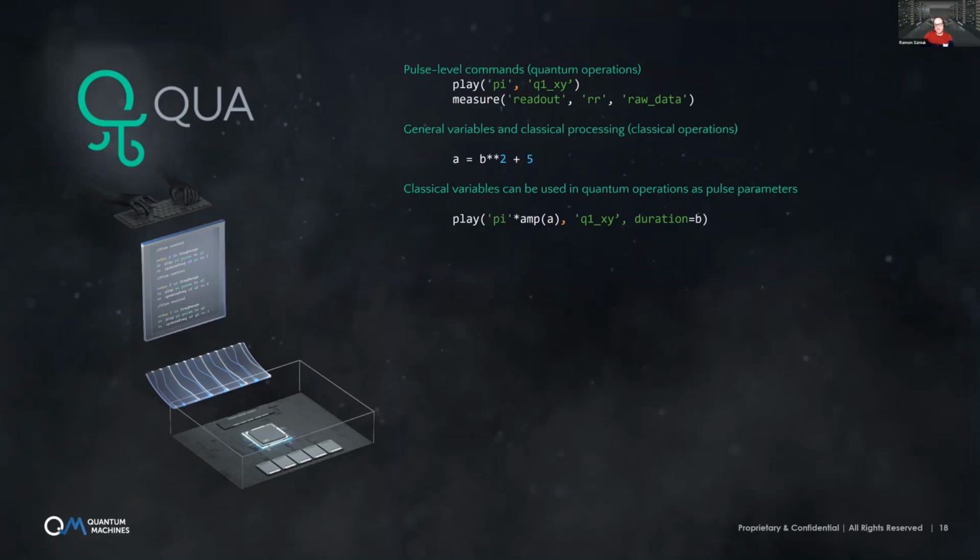And if you decide mid-circuit that you want to make a 1 microsecond pulse, then you can change the duration of the pulse here, and the pulse processor will perform a third order Lagrange interpolation in real time on the envelope and output a 1 microsecond signal. Of course, the carrier frequency inside will still be the 100 megahertz or whatever of this qubit. It's just the envelope that is stretched.